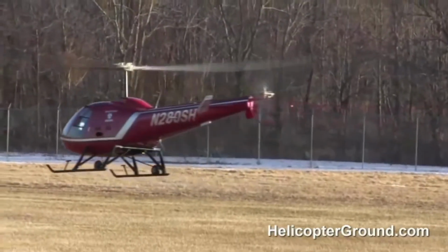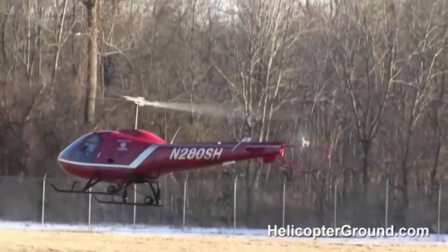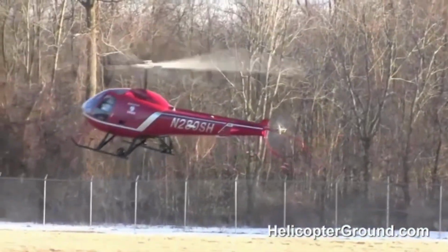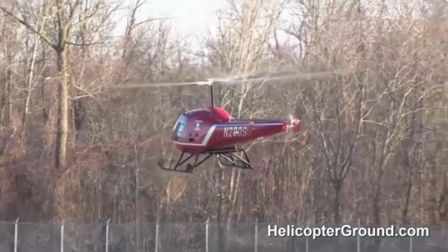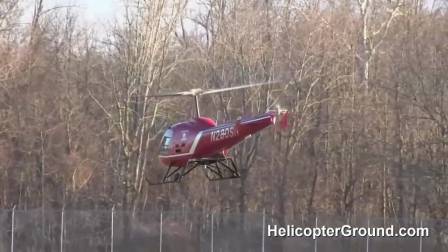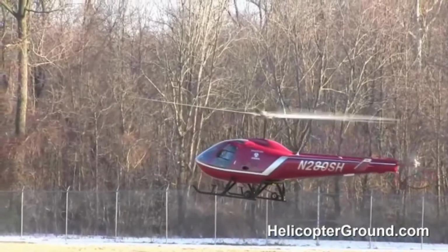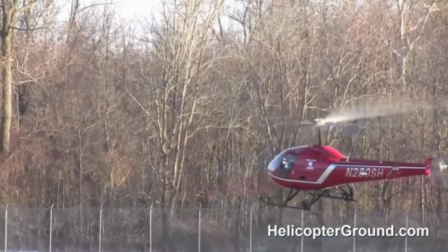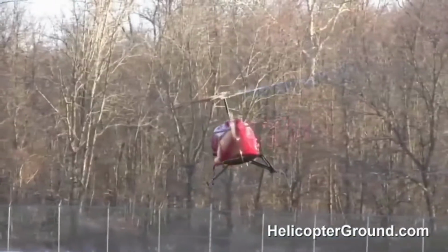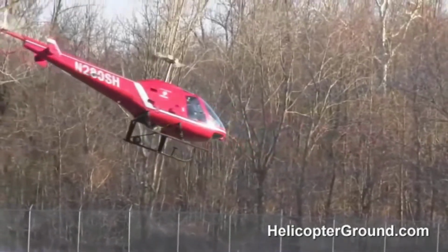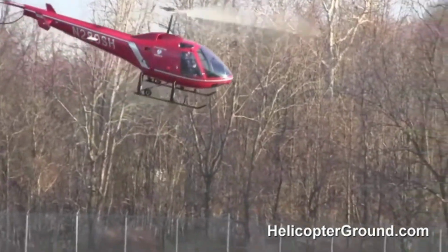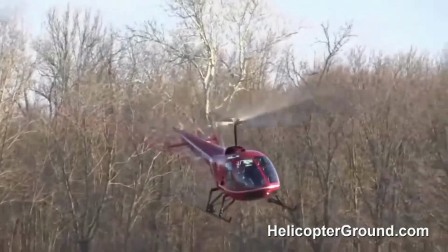One of the things that you'll learn about is pendular action. And you can see that in this video. Anytime that they're out there, as it starts to move, it'll start swinging. It'll go forward, and then it swings backwards. Maybe it goes to the left, and then it goes to the right. That is what we call pendular action. And that is a normal thing that you're going to go through when you're learning to fly these things. You're going to just be swinging that aircraft, swinging left, swinging right, swinging forward, swinging back.